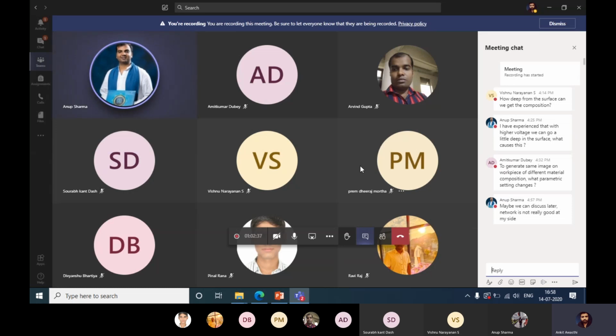But generally the operators don't provide you these details, right? Yeah, they don't. I haven't heard all these terms. So many times I have seen that if some TA is performing these experiments and is not able to get the image, they call the main project staff and say, ma'am, this is the issue. Ma'am will tell them to increase the working distance, decrease the aperture size, or increase the accelerating voltage, but they also don't know the reason behind this. They just know we have to set this in this range. So that's the main thing.